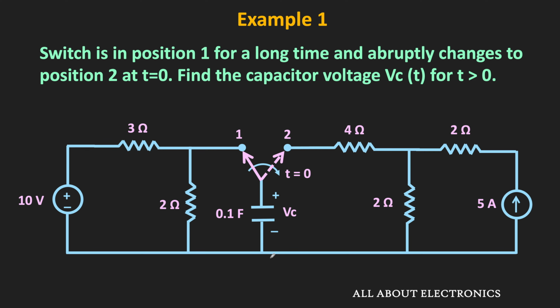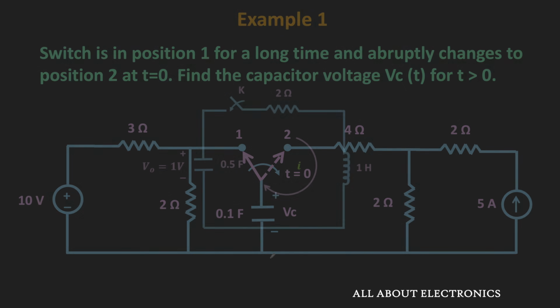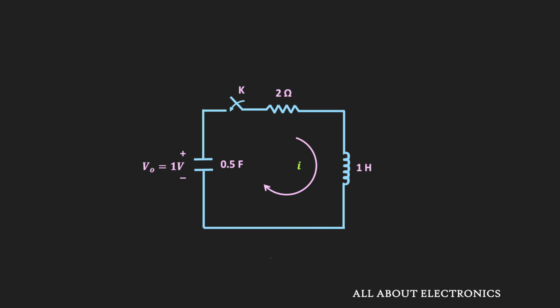And for first order circuits, if you want to find the transient response, then we can even use the conventional method. But as we go from the first order circuit towards the second order circuit, like the second order RLC circuits, it is difficult to solve using the conventional method. And for such second order circuits, it is always useful to solve them using the Laplace transform.